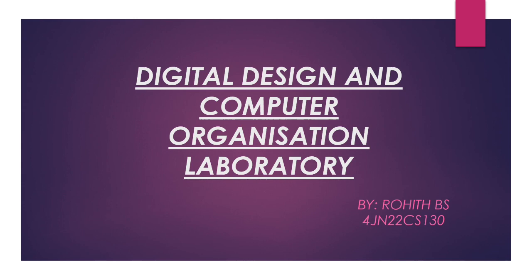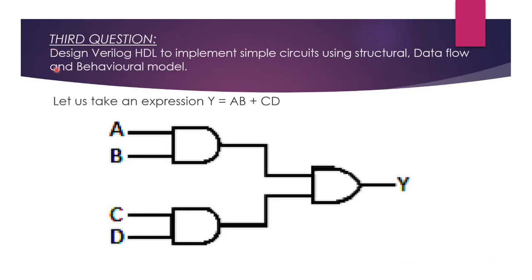Let's get into the topic. The third question is to design Verilog HDL to implement simple circuits using structural, data flow, and behavioral modules. They have also given the expression Y is equal to AB plus CD, which means that we have to obtain the Verilog HDL program from this expression, and we should write the circuit, which is also given here.